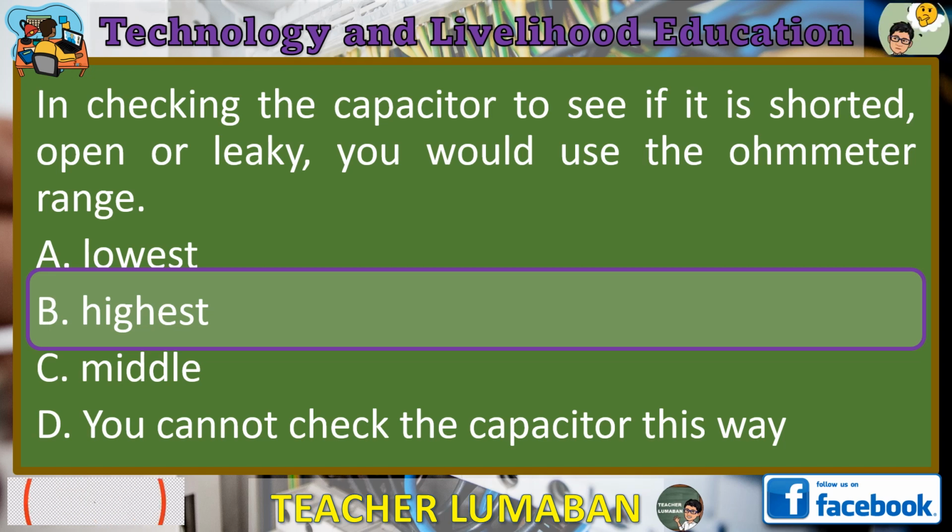Reverse the leads. Disconnect the probes from the capacitor and reverse their connections. Connect the positive probe to the negative terminal and the negative probe to the positive terminal.